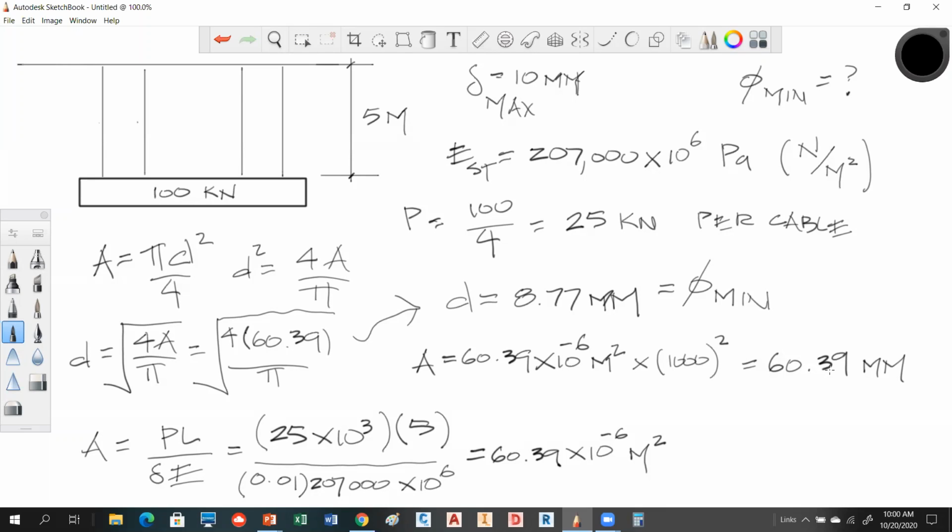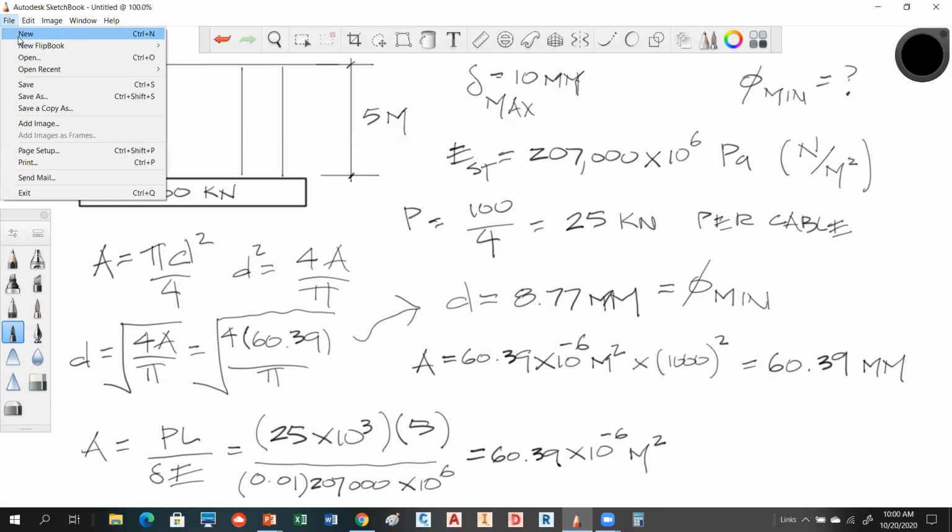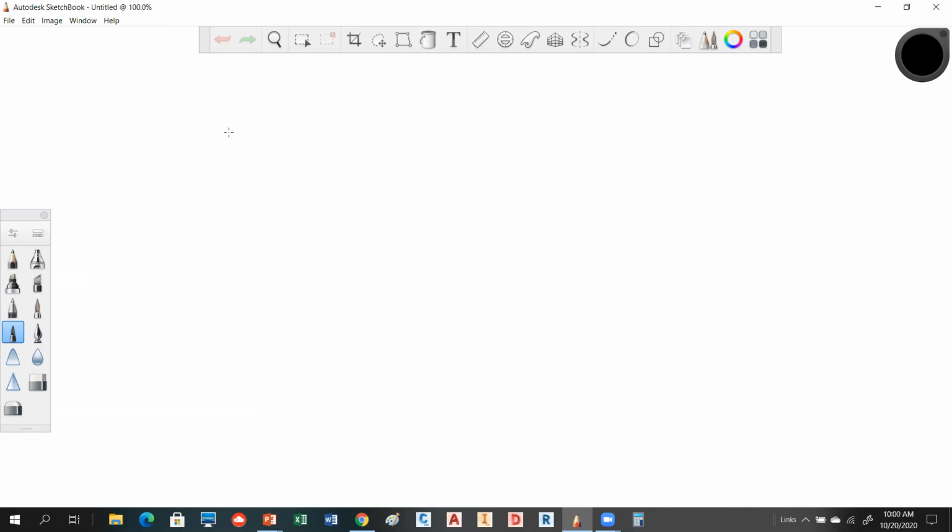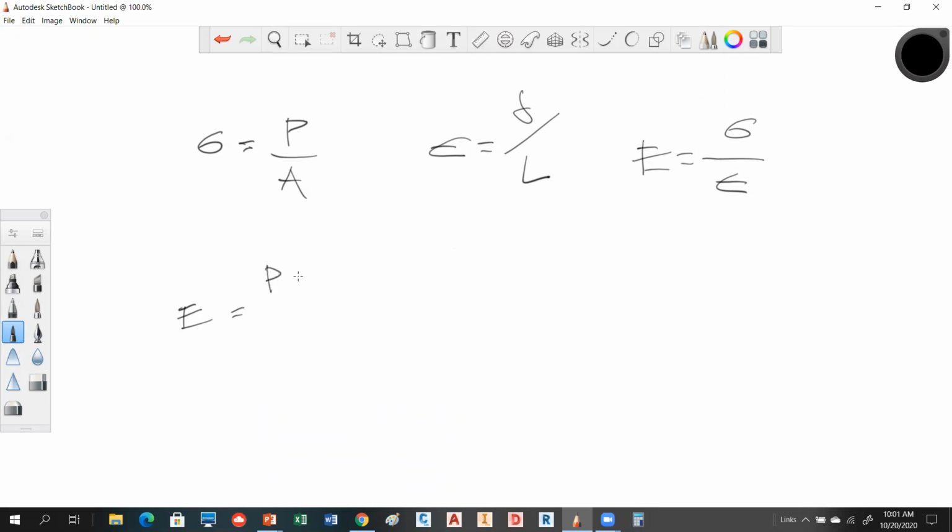We're basically using 3 equations and just manipulating them to get what we need out of it. All 3 are key equations, and I'll just do this real quick, hopefully this will help. Stress is force divided by cross-sectional area. Strain is deformation divided by original length. And E is stress divided by strain. From those 3, you can get literally anything you want. Because if I replace in this equation stress with its definition, I get P over A, and strain with its definition, deformation over L. And then that can get cleaned up. So the middle one is deformation? This is right here.